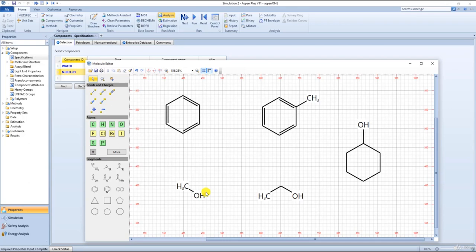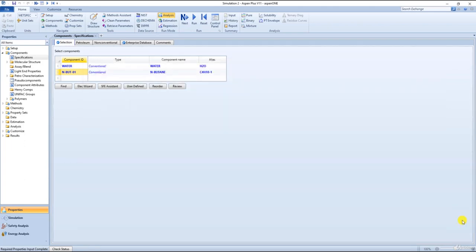From solution thermodynamics point of view, the non-ideal liquid mixture can be described by introducing the concept of fugacity, which basically accounts for the effective thermodynamic presence of a specific species in a solution. This means that its thermodynamic concentration not only reflects its count, but also extends to include its social interaction with its neighbors, the so-called activity coefficient. So, this was a brief description of the activity coefficient-based method.